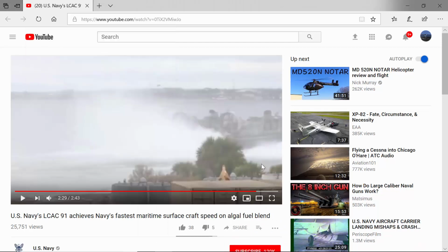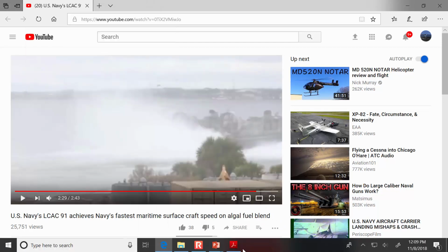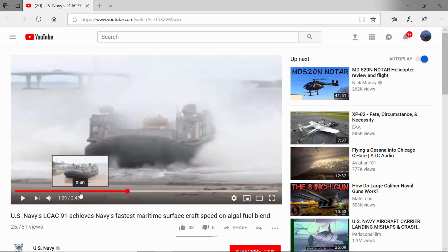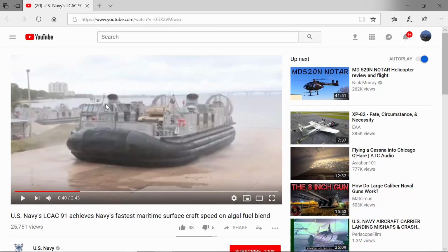This is a perfect example of momentum and fluid mechanics because not only is it having to do with these thrusters, which is allowing it to steer, but the forward thrust is all about fluid momentum. And then you're also riding on a cushion of air. And so you think about, we said 185,000 kilograms of weight. So that all has to be resisted with pressure times area on the bottom.